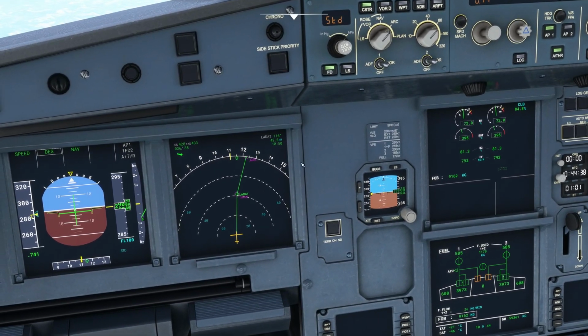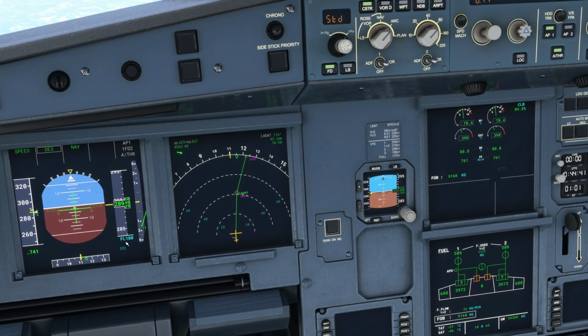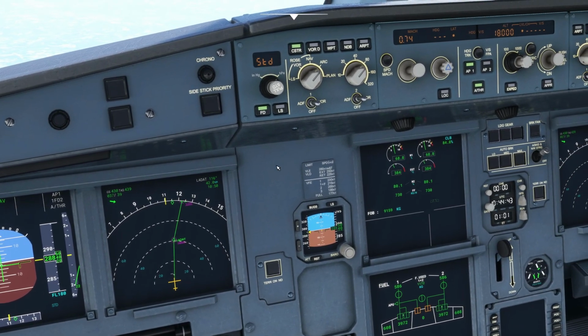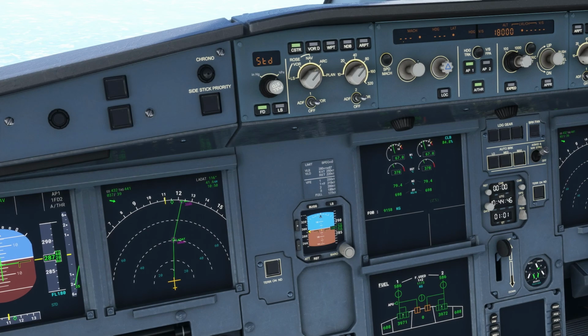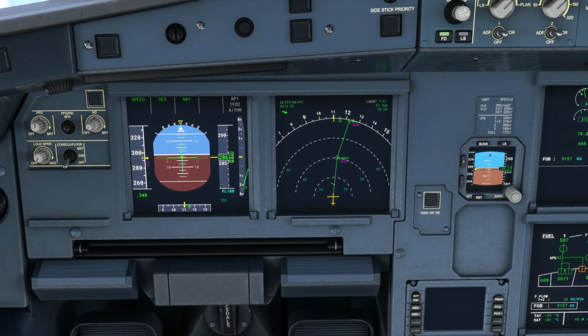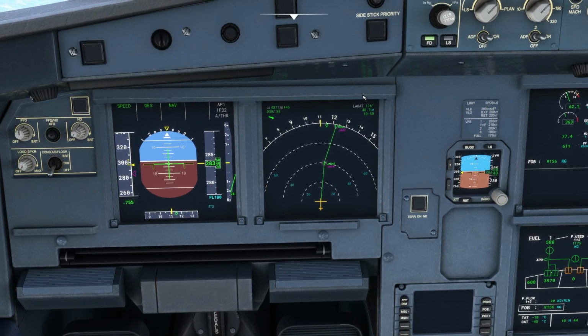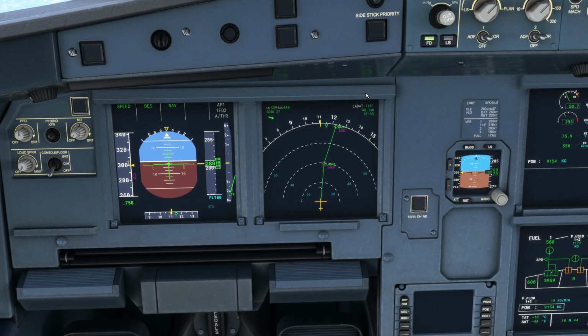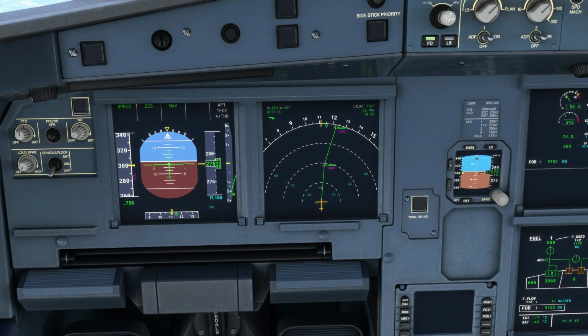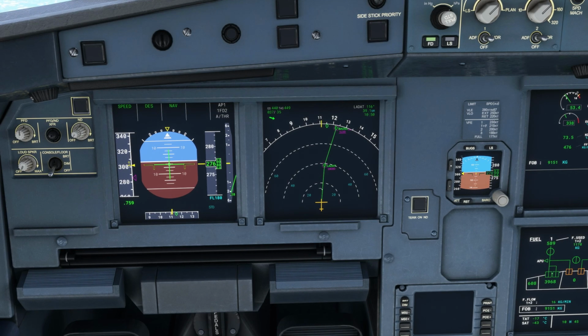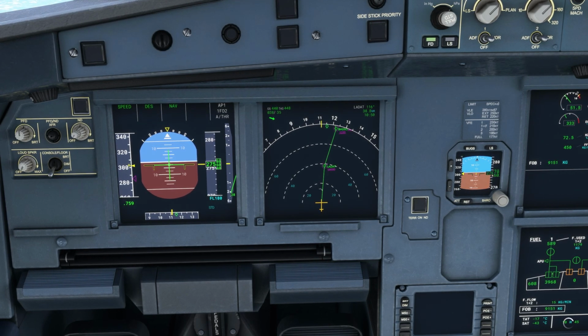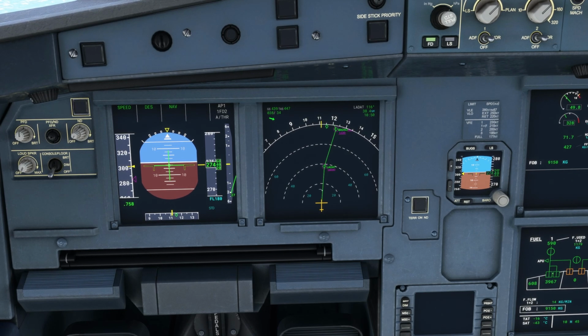I've pushed the altimeter, so the aircraft will now take control of the descent itself. Let's just give it a minute or two, it just needs to settle down, and I'll give it control of the airspeed as well. Our calculations showed we needed a descent rate of about 2,200 feet. The descent rate's bouncing around a little bit at the moment, but it's probably going to settle around 2,700 feet. So it's going to bring us down a little bit early. While we've done it, so we'll live with it, but for further descents I think we'll do it manually. The transition altitude in Germany is 5,000 feet, so we will remain on standard for this descent.